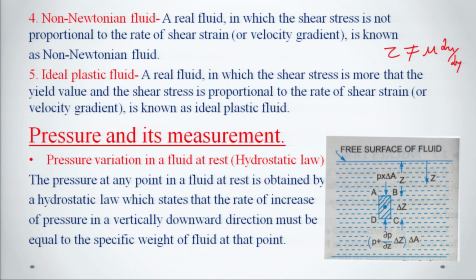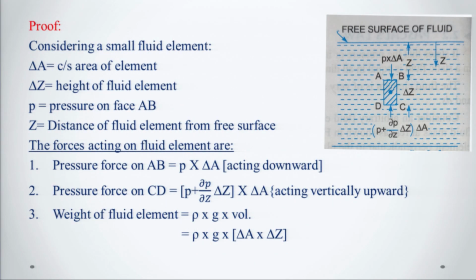So, we will have the derivation of the hydrostatic law right now here, and by that you will come to know how this statement will be fulfilled. Okay. So, here if we have a point inside a liquid, this is the free surface of the liquid we can see, and just take the elementary volume near the point like this, we can say the shaded portion, it is the elementary volume having the face A, B, C and D.